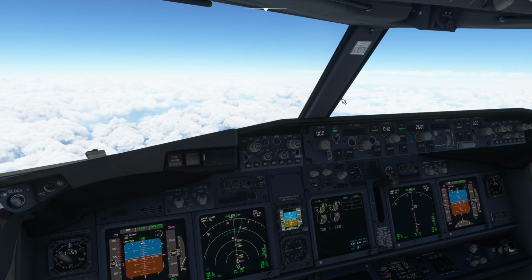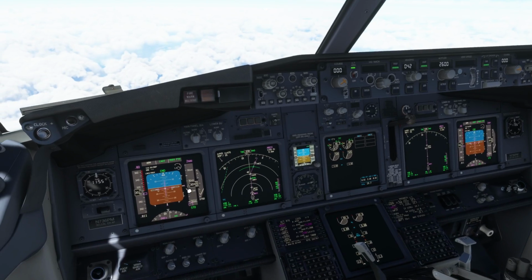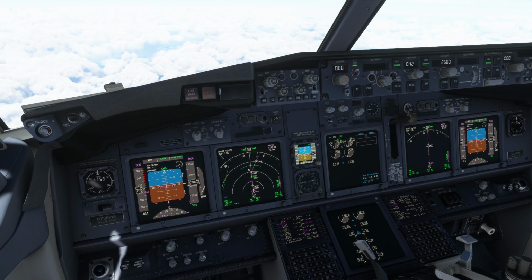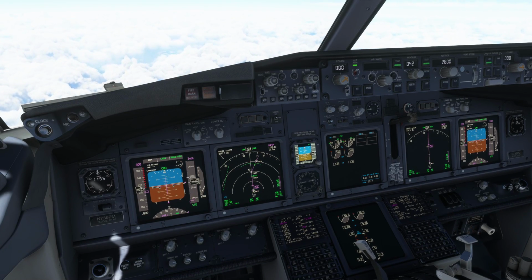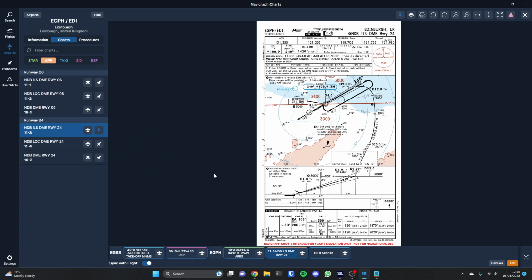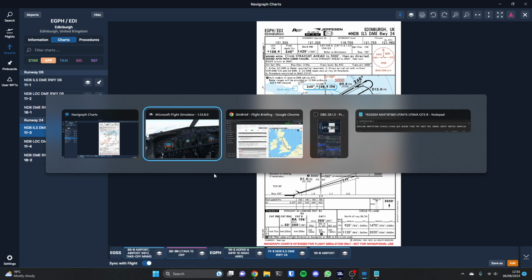The only reason this is important is the point at which you retune your barometric pressure to the barometric pressure at ground level of the airfield. So in our case, we can go and find that out.